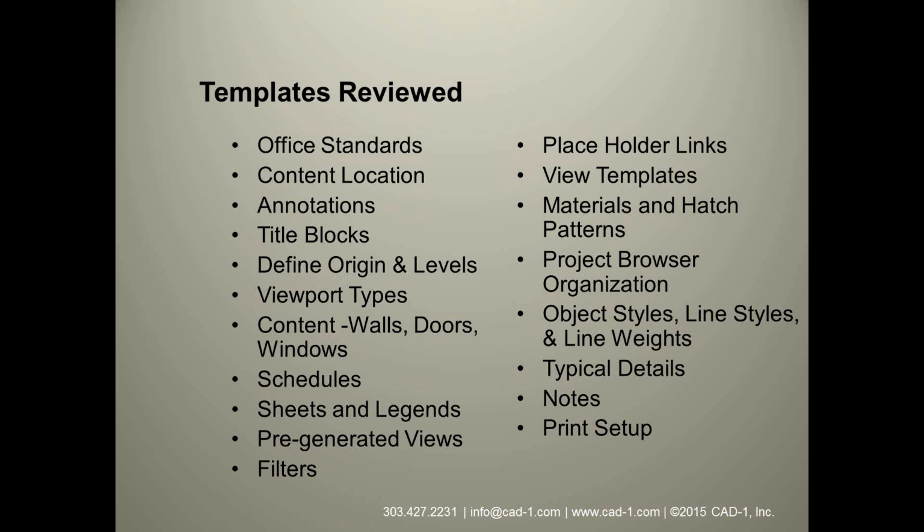Let's see. Jason asks, if it is a sheet, you can access the project information. That's really more of an information parameter. I think that was back when we were looking at the start sheet. Yeah. And when you're using a starting view as a cover sheet, Jason likes to use the cover sheet because it has the project information parameters, the address, the name of the client, things like that on there. So when you start out that project, that's a great place to start. I like the starting view as notes, but either way is going to be great. So that's awesome.